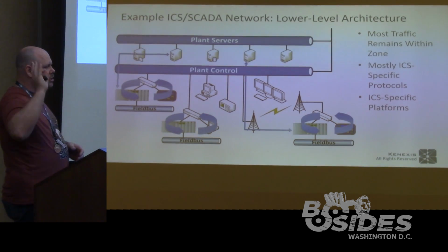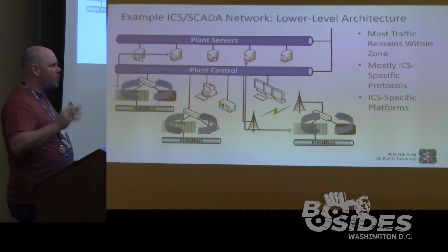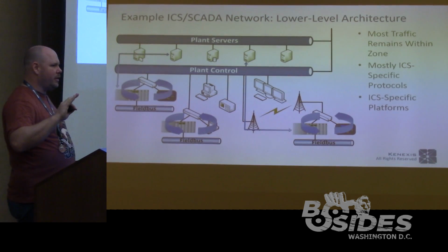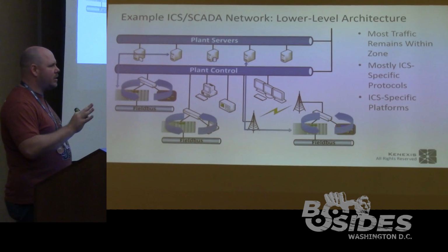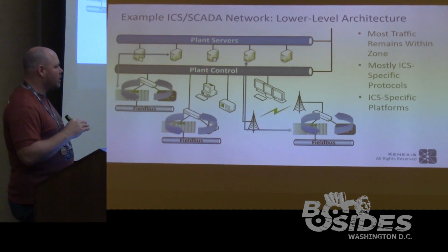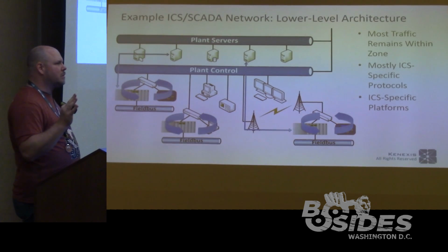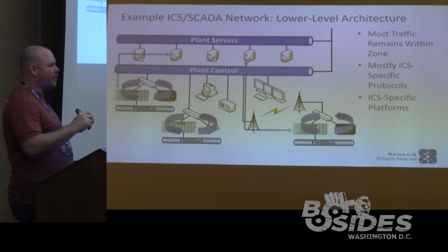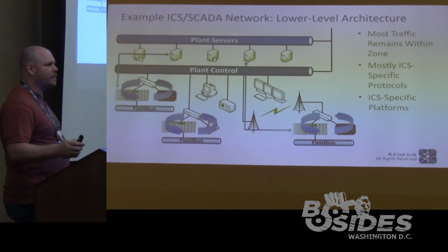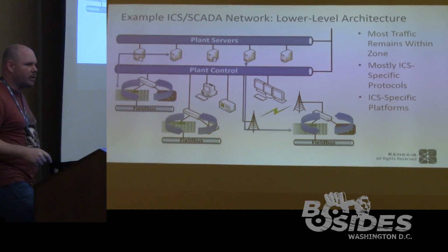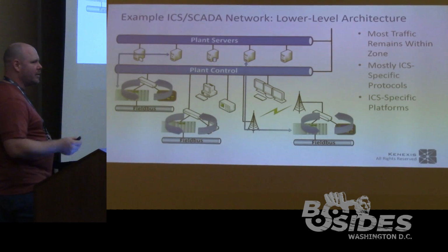When you deal with large-scale SCADA systems like water utilities, wastewater, power plant utilities, pipelines, things like that, sometimes you're dealing with like 1,000 independent, isolated networks because you've got that many substations in your network. And each substation gets its own separate segmented network so that it doesn't transmit back to the main network.